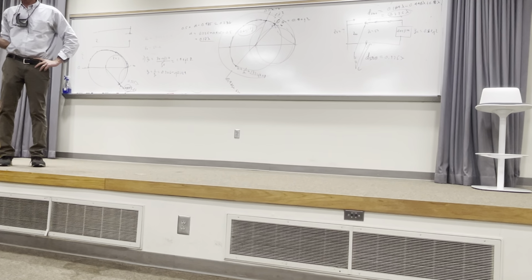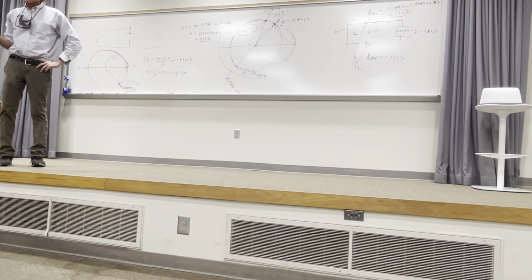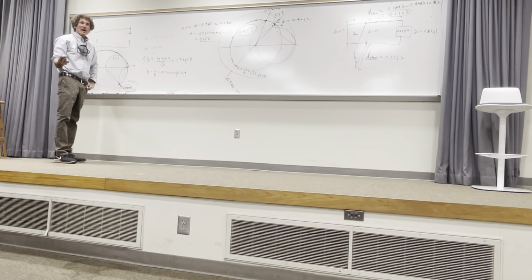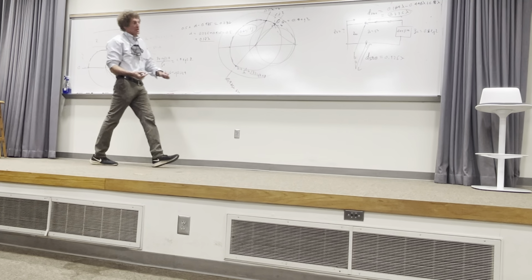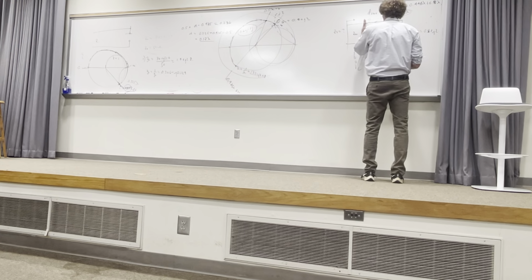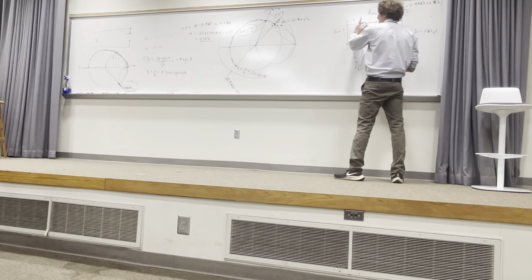Now I've got the normalized value of Y at the point the stub was connected, right? And what was the value of the stub's admittance? What did we get? Minus J 1.9, right? Yeah. So now what we're going to do is add these two together. This admittance right here was minus J 1.9, and we're going to add it to that value.